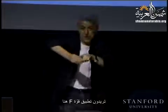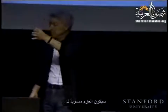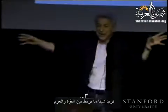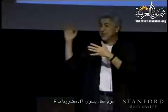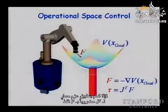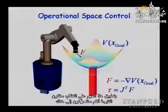So you want to apply a force here, F. What would be the corresponding torque? So it will be torque equal... We need something to relate this force to the torque. J transpose F equals torque. That's it. So if you just apply a J transpose F, where F is this gradient of your goal position in X, you apply this to the system, and the result is going to be that you will move there. And it works.